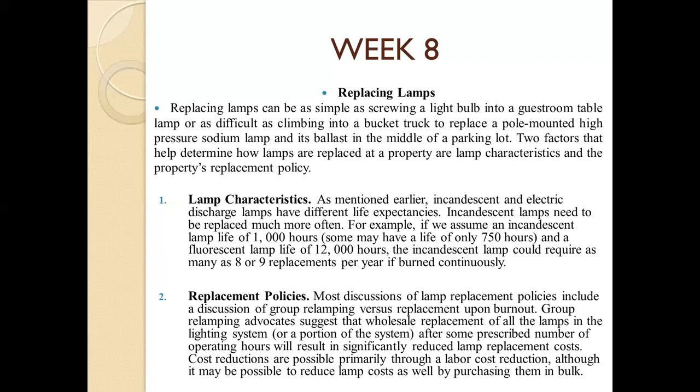So in your handouts or PDF files, we may see a lamp replacement policy in a figure that we have. We have here sample lamp replacement procedures, so you may read it. Basically, group relamping is appropriate in any area that requires a significant number of labor hours to gain access to the lamps in the system. For example, we have the convention halls and parking lots. These are great for group relamping.